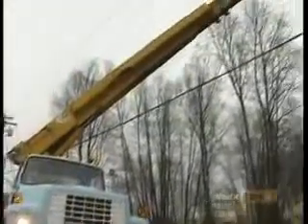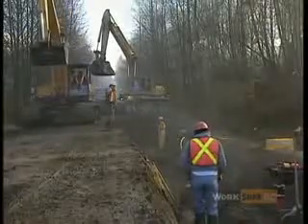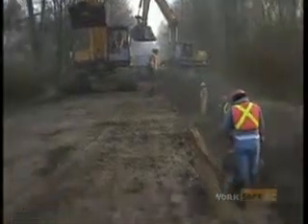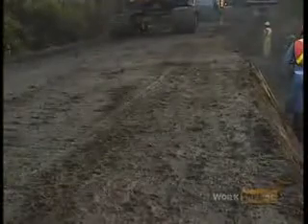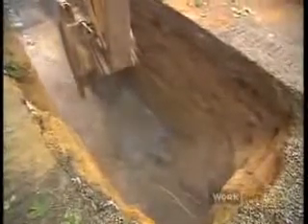Trees, utility poles, rocks, or similar objects in the vicinity must be secured or removed, and a clean, level area extending 2 feet back from the edge of an excavation must be maintained. The side of the excavation must be trimmed or scaled to remove any loose material or rocks.